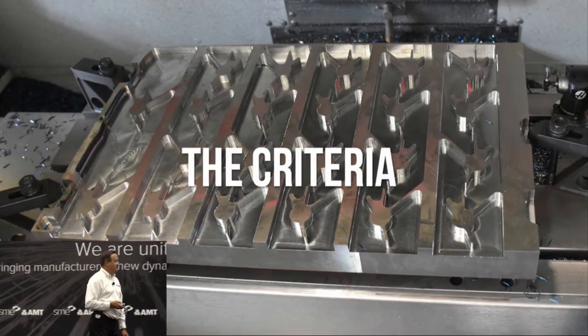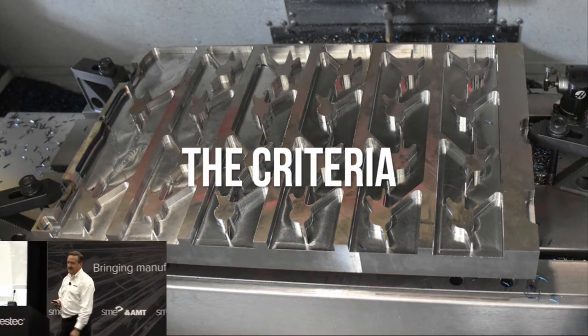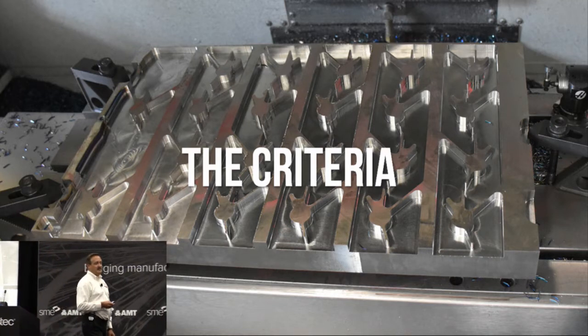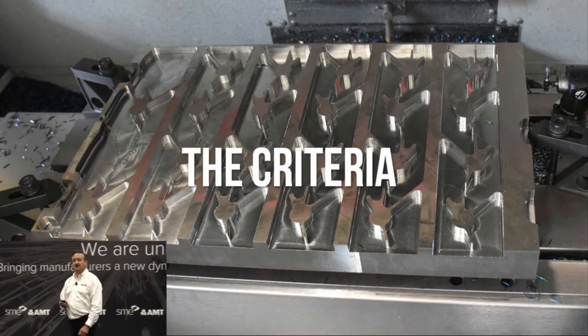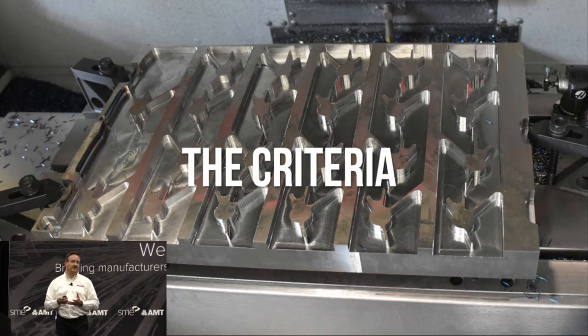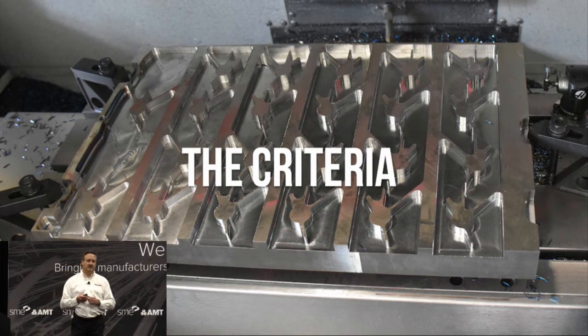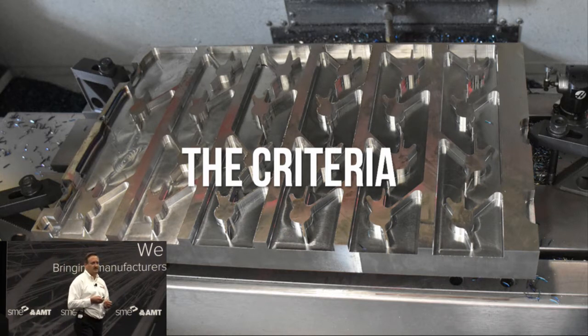Okay, so the criteria. Here's our sample part. Now, this part was a piece of D2, okay? So you're looking at 31, 32 Rockwell. Not really hard, but challenging enough. The geometry in that specific part was designed for a specific reason. We wanted to make sure we got enough travel. We're going to be running a 3/8 inch tool through that material. We're going to go a 1/2 inch deep, so just a little bit over a 1/2 inch. So we're running about 1.5 times D.